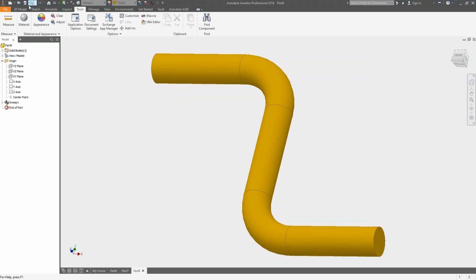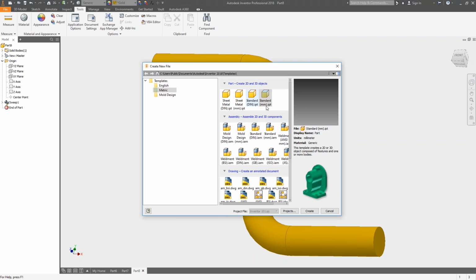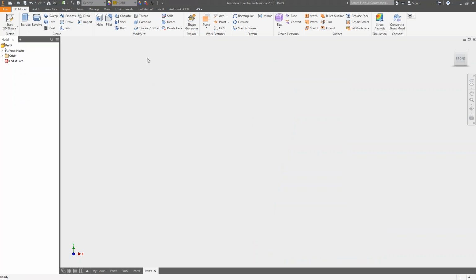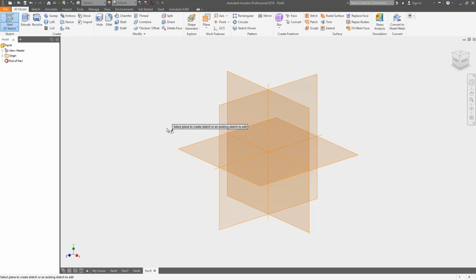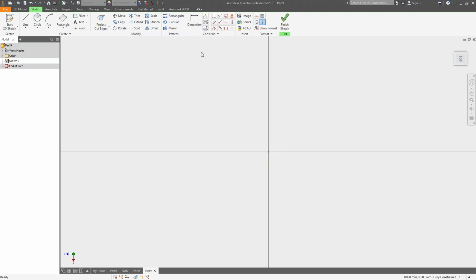So this is something that happens all the time in Inventor. This isn't a one-time thing for this part file. So when I go to create a new part file, and I want to do a sketch, S for sketch, on this plane, and I want to do a 2-point rectangle, I just do 2P, it issues my 2-point rectangle command for me, and now I have a 2-point rectangle without hunting for the command, without looking for anything else.